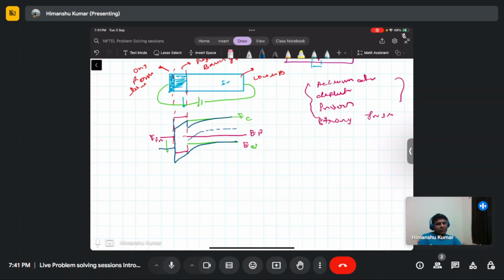The interface at this oxide junction is becoming more n type, because the conduction band is becoming closer to the Fermi level. Electrons in this p-type substrate will come by depleting the substrate.